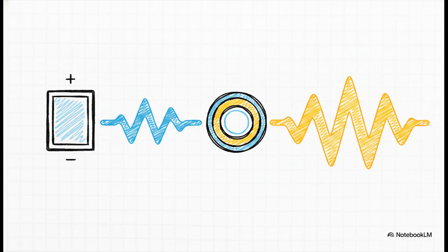It's actually a very elegant relationship. You pump more excitation current into the generator's rotor, you get more voltage out on the network. If the voltage gets a little too high, the AVR just pulls that excitation current right back.